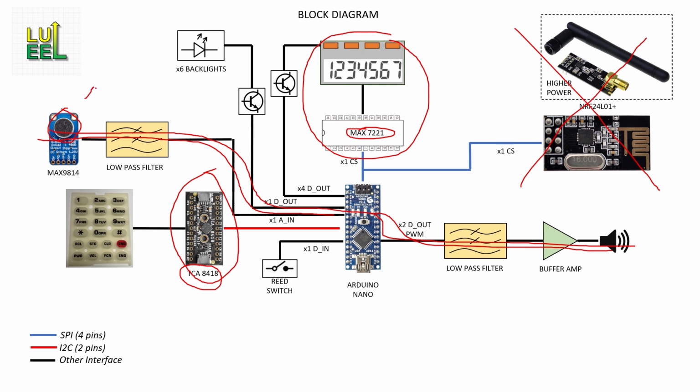The raw output of a microphone is an AC signal that varies in amplitude and frequency, corresponding of course with the audio that it senses. We cannot feed that AC signal directly into the ADC input of the Nano for several reasons, starting with the fact that the microphone output typically has 0 DC offset. So approximately half of the signal is negative with respect to ground, and the ADC cannot sense below ground. So it needs to be DC shifted. It's also a very low level signal, and we'd only be using a tiny portion of the ADC's resolution.